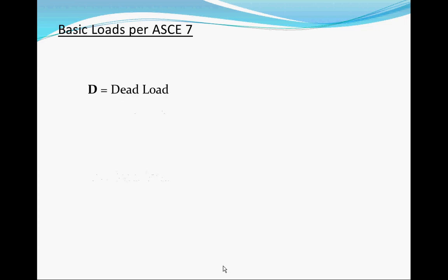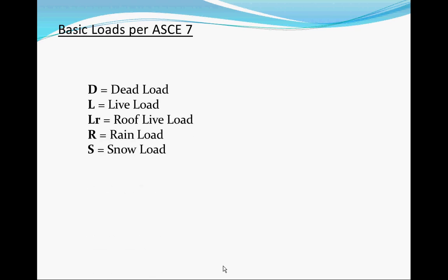So also you have other loads to deal with. The dead load, live load, roof live load, rain, snow, or wind. Wind could be lateral or it could be sucking up the roof. The weight of the building W is the dead load, the whole dead load, like how much this weighs. Live load is people walking around or whatever. Roof live load is on the roof. So they'll tell you what to use.